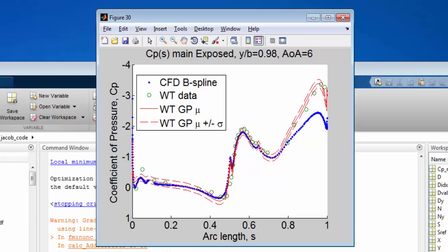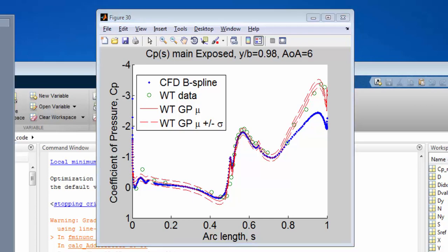The Gaussian process models are one-dimensional surrogates, in this case, along the wind tunnel pressure port bands. This work uses multiple 1D or one-dimensional Gaussian process models at the port bands and then uses an additive corrector method to calculate the two-dimensional wind tunnel surrogate. Let's look at that.